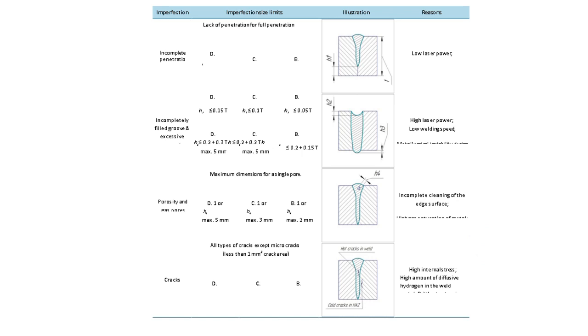Thick section laser beam welding has lower line energy, down to 5 joule per millimeter, compared with traditional arc welding or laser arc hybrid welding, and the highest cooling rates are up to 3000 degrees per second. So efficiency increasing solutions in research focus not only on increasing the process efficiency, but also on reducing the probability of defects occurrence.